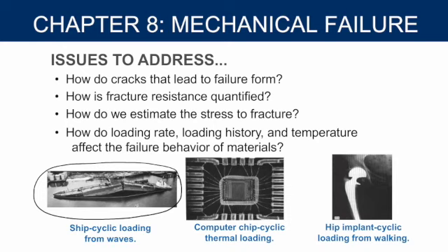This occurred because the metals actually went through a transition, and it happened to occur at a much lower temperature. The engineers that created these boats didn't think to test lower temperatures, close to freezing of the water. They had tested it all at room temperature values.